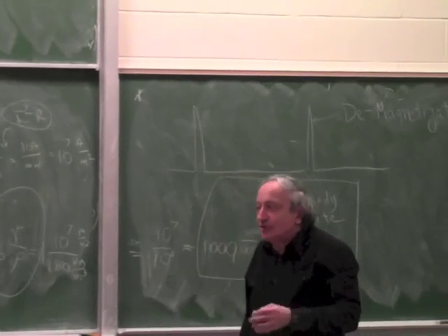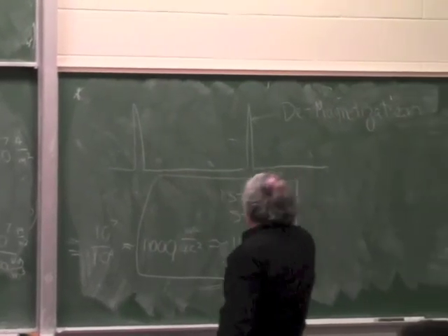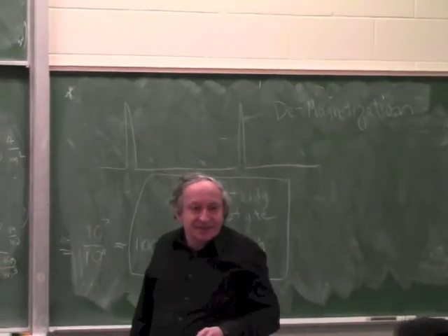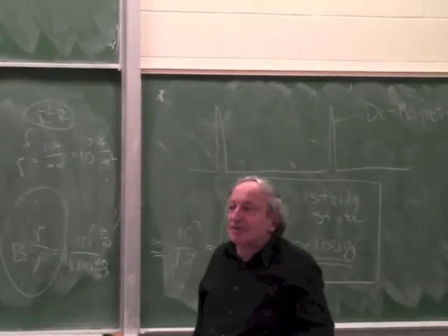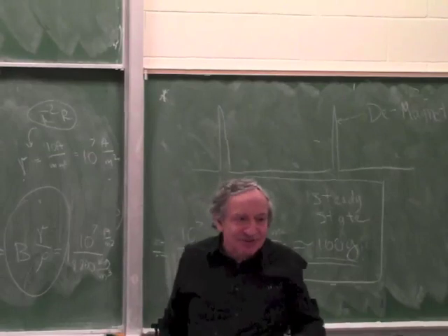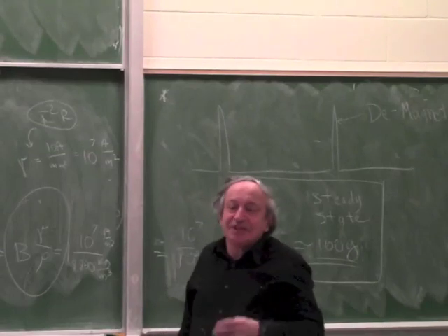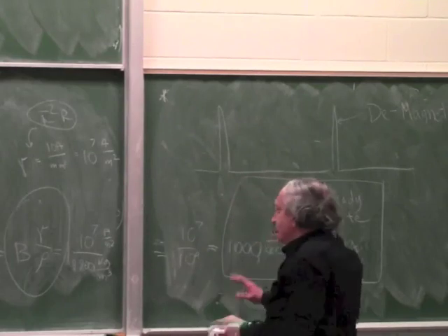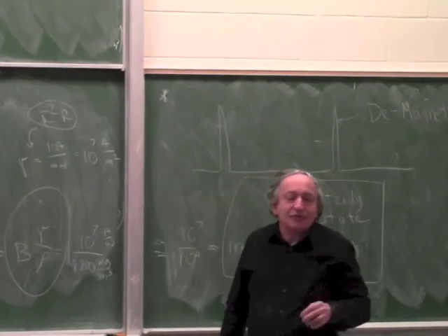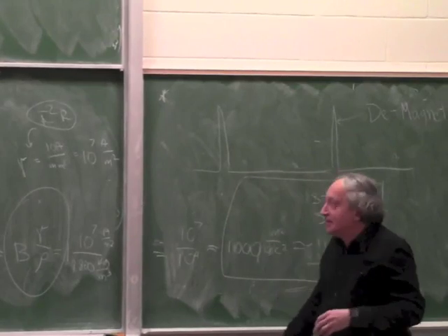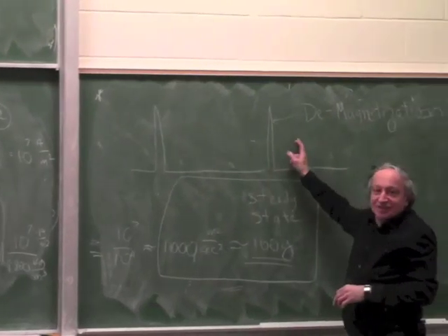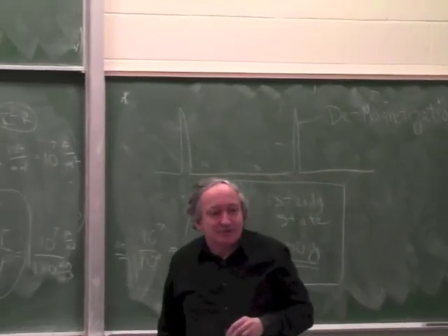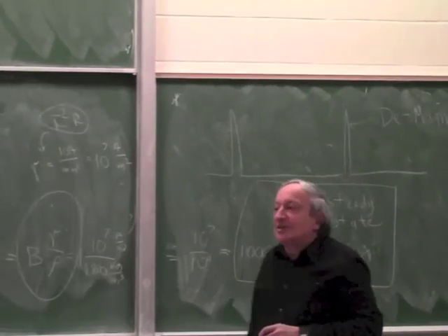If you force cool it, you can increase this number a lot in steady state, and that's being done. That's being done, for example, in very high performance electric motors, where you really need the performance and you can't afford the weight, so you force cool it. But this whole calculation is without cooling. If you use force cooling, you hit this next limit. Even in steady state, you'll demagnetize. There's many force-cooled electric motors for high performance.